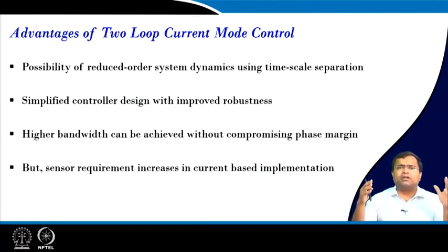If you are going for high frequency application, then there can be some problem in the current sensing. But if you go to integrated circuit, that means IC, then you can actually play with various current sensing techniques. You can sense just the high side current by means of RDS on of the switch. You can use some kind of a current mirror and you can sense the current.